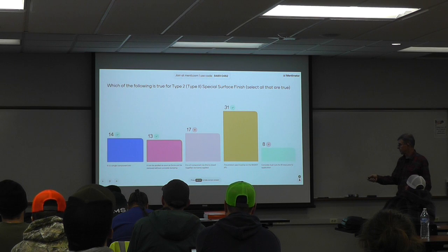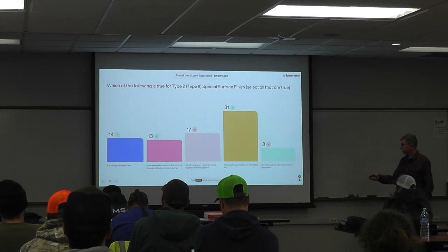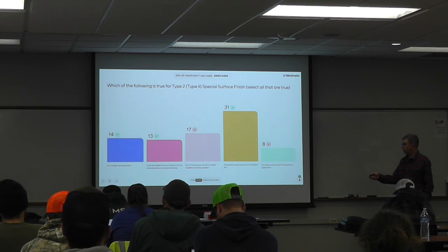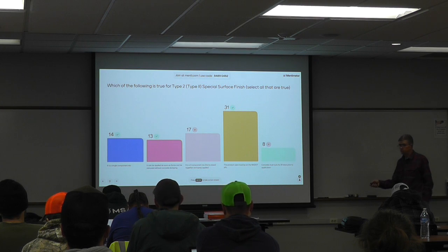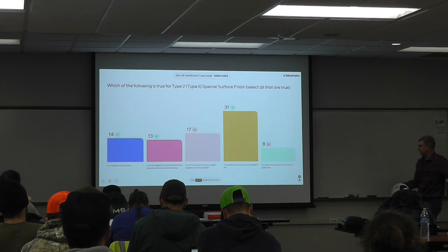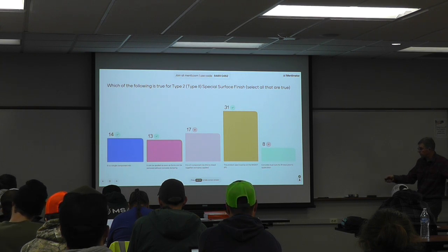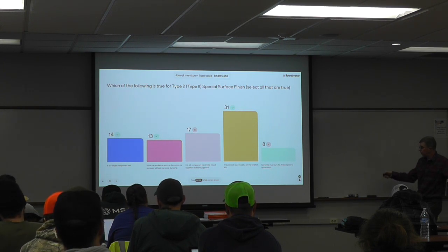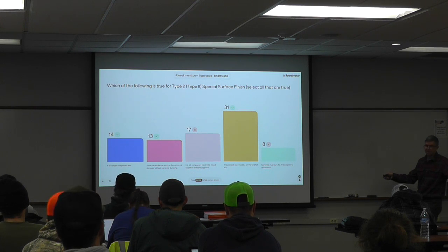A 2-component mix, no, it's a single component. So SSF2, single component. Must be on APL, yes, that is true. And the concrete must cure for 28 days, no, that is incorrect. It can be applied as soon as forms can be removed. The older products had a 28-day cure, but not the SSF.